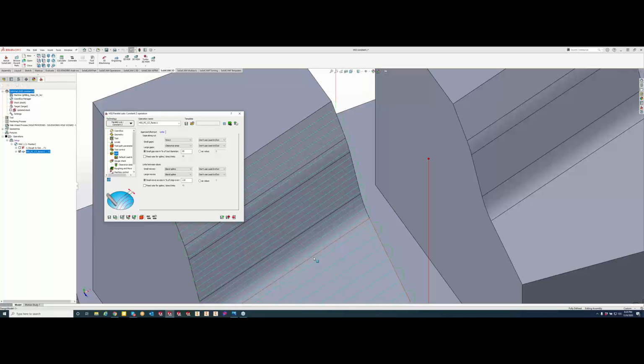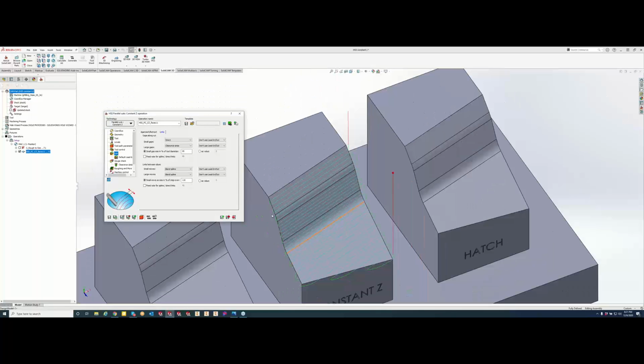And now we've got a nice smooth tool path going through there, and you will not get any of that machine jerkiness going on there, because we're not doing an exact X movement and then a sharp Y movement. We're doing a nice arc working its way around it. Okay, so that one is a big one.